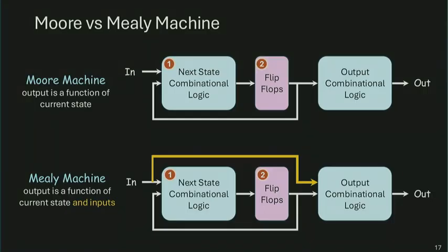All right. And sequential circuits, in general, can be modeled in different ways. They correspond to 2 different types of state diagrams. Number 1 is called a Moore machine. Number 2 is called a Mealy machine. They sound like very fancy words, but the only difference is whether the output logic depends on just my state value, or also depends on my current inputs. What we saw earlier from that T flip-flop parity counter, the output is the state output. So that is a Moore machine, right? Input has no impact directly on the output behavior. Whereas for a Mealy machine, you're going to build a more complicated combinational logic that takes both the current state and the current inputs.